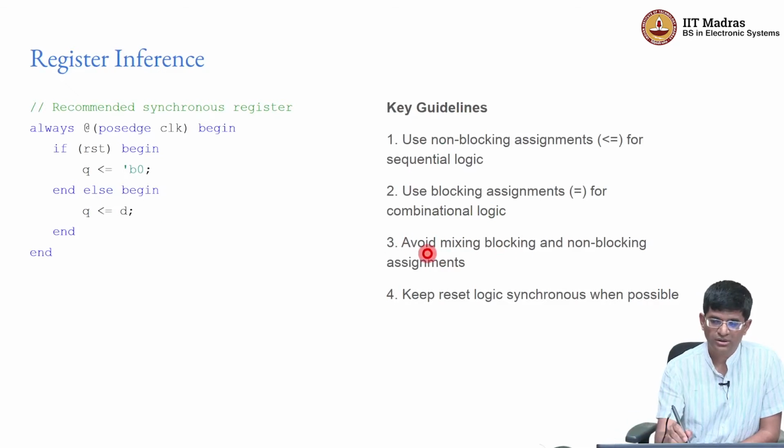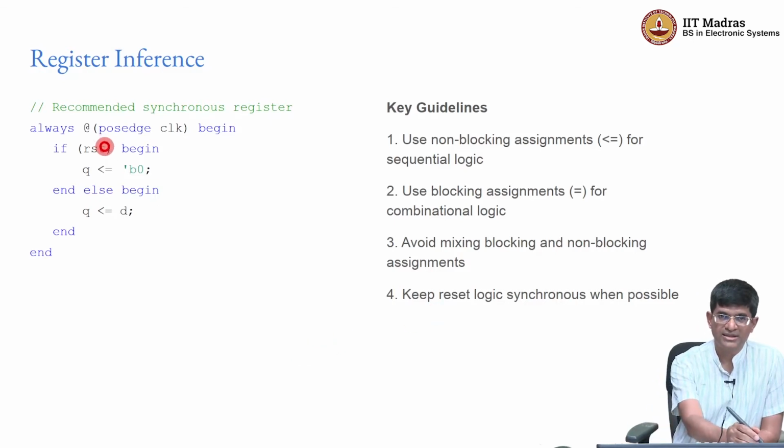No matter what, avoid mixing blocking and non-blocking assignments inside the same always block. There is never a good reason to do this. And again, as a matter of convention, keep the reset logic synchronous when possible, right? This basically means don't have the posedge reset over here.